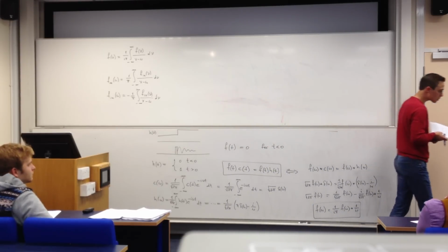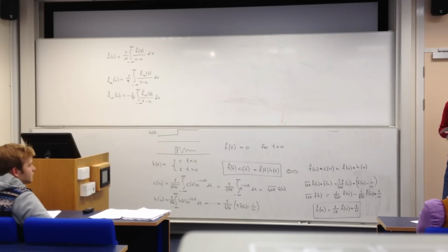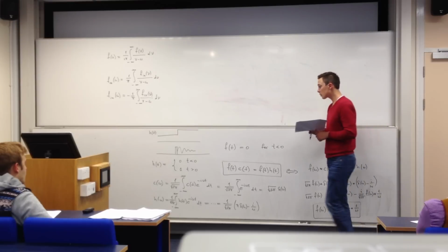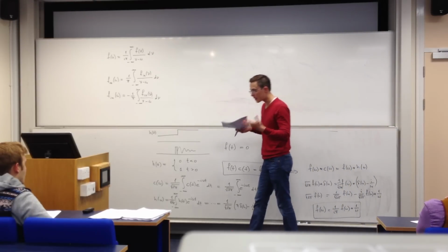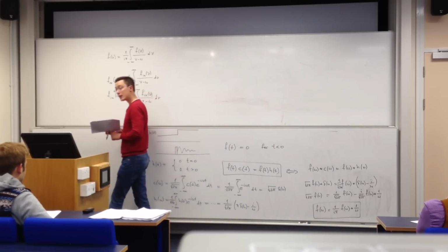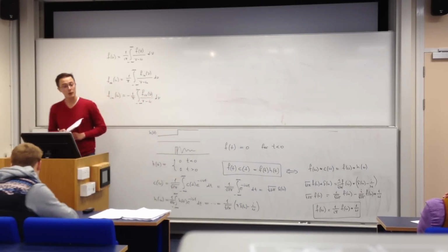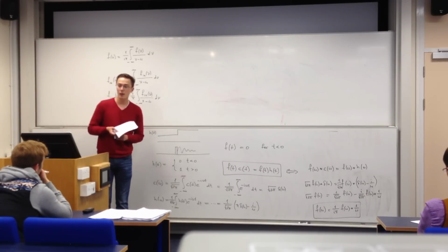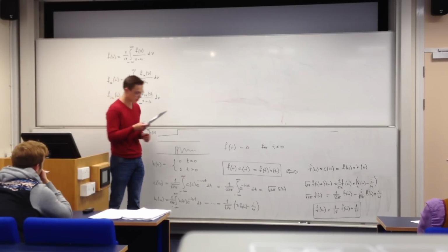But what is also true, and that is unrelated to the complex phase, is the detection circuitry of the spectrometer and the practicalities of giving a pulse to a system means that the signals that we get out of the spectrometer would often arrive multiplied by basically an arbitrary complex exponential.